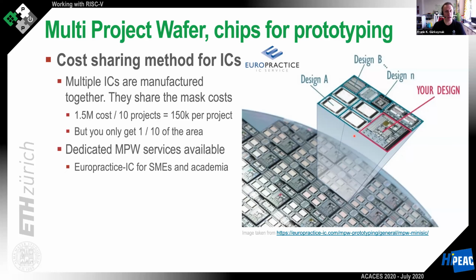There are services like Europractice IC, which has been very helpful for us, and I've taken the picture from their website that explains this. This is the reserved area, the reticle. This is the repeat pattern that goes onto the wafer, and it is shared among 10, 20 designs. Each one of them contributes to the upfront cost in accordance with their area. They announce dates when these are available, you register for them, you pay the price.